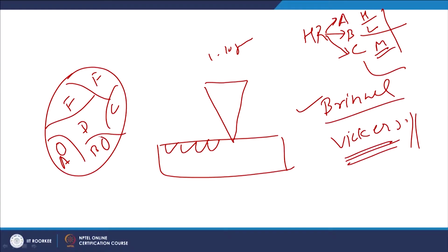So, through micro hardness we can check the hardness of each of the constituents easily, so that the hardness of each constituent is identified to see what are the tough or ductile phases present and what are the hard and brittle phases present in the given material. So, this is about the hardness, and what are the things which are influenced by the hardness.